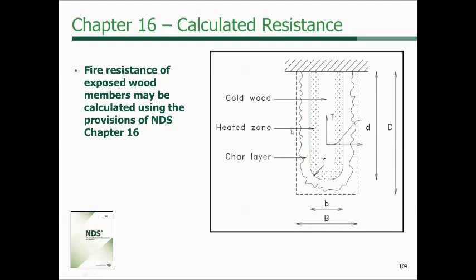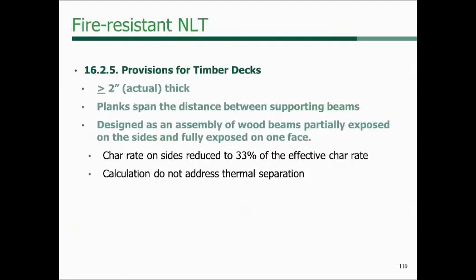And we can calculate using the equations in the NDS how much char layer we'll need to provide a certain amount of fire resistance. A rule of thumb is 1.5 inches of wood member is equal to 1 hour of fire resistance. So in essence, you're building into that wood member a sacrificial layer that will burn away. And then once that layer is burned away, you check the structural capabilities of that member after it's been charred or burnt or exposed to fire.